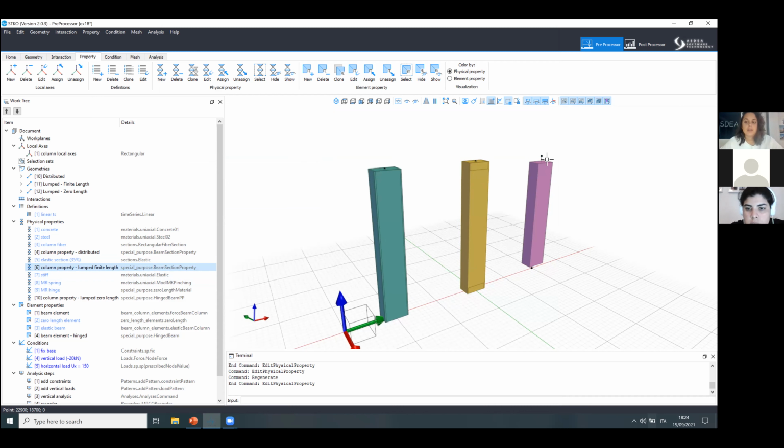One thing that's very common, if you have, for example, a large structure, but you have some typological sections, what you can do is model those sections small and make this kind of experiment, simulating what's the moment curvature response of a single column with that type of section, and then extract the moment curvature response of that column and use it to calibrate the spring parameters.